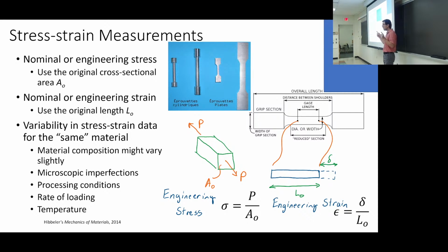One, milling can be very tricky for internal sharp edges. External sharp edges you can get pretty easily with a mill, but for internal sharp edges, the mill has a particular diameter, so you can't get in there. But coincidentally, or maybe not, it's actually advantageous that you don't put those sharp corners in, because that's where a crack can begin to open up and you can get failure.